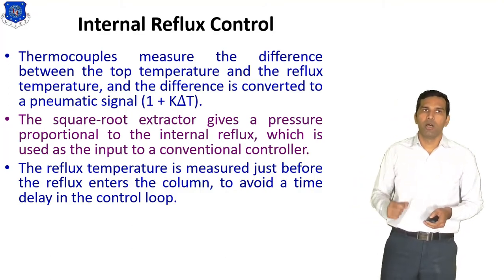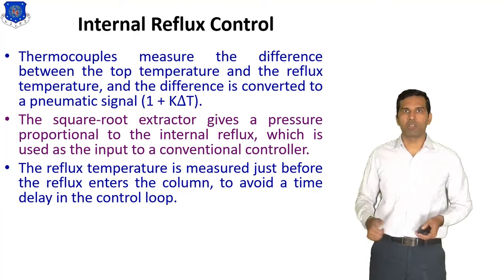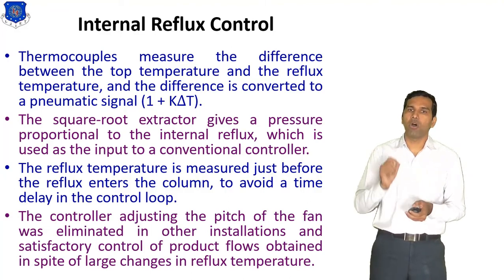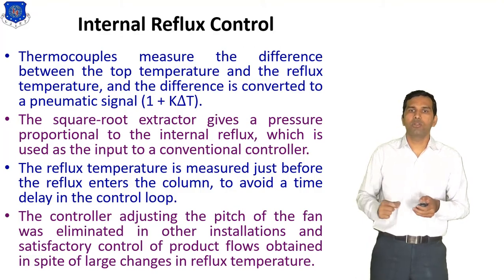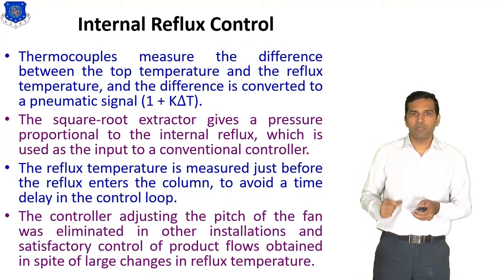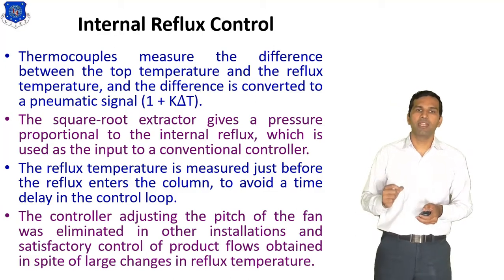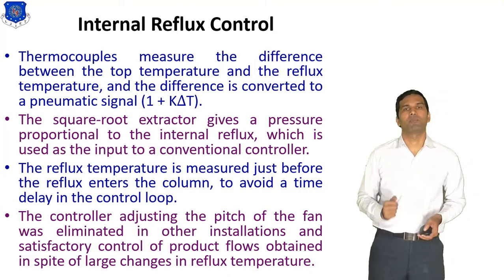So here we avoid the delay that is produced due to the measuring process. The control adjusting the pitch of the fan was eliminated in the other installation, and satisfactory control of the product flow was obtained in spite of a large change in the reflux temperature.